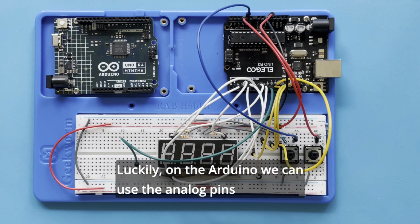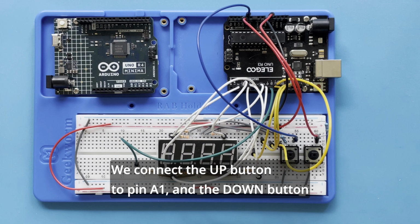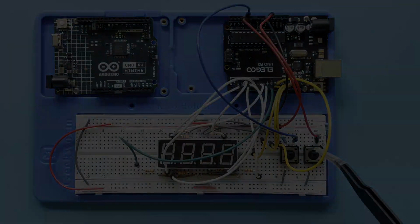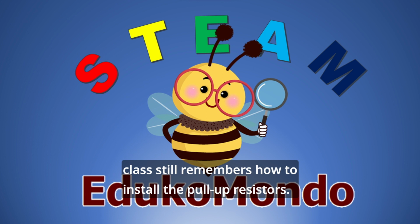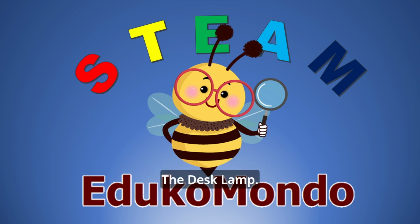Luckily, on the Arduino, we can use the analog pins as digital pins. We connect the up button to pin A1 and the down button to pin A2. Here you can pause for a moment to check if your class still remembers how to install the pull-up resistors. If not, let them revisit lesson number 10, the desk lamp.